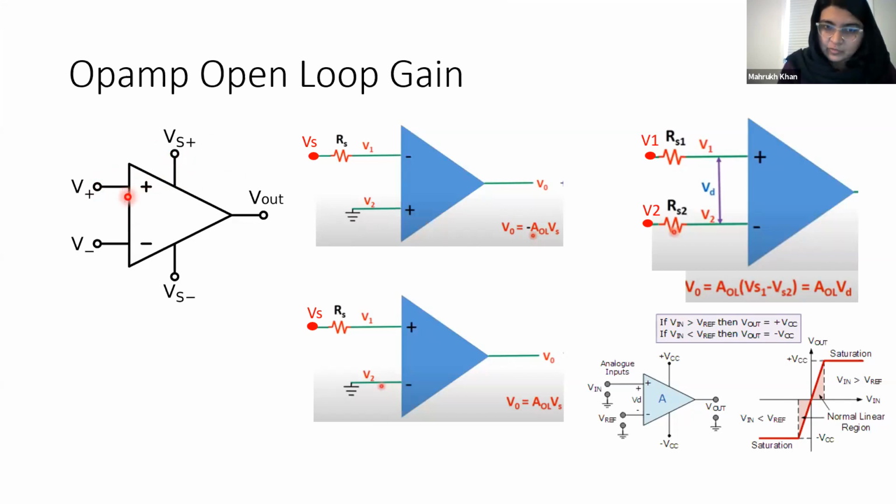If it is less than 12 volts, it will give you the logical result. Like if the output is supposed to be 4 volts, it's fine. But as soon as it becomes greater than VCC or minus VCC, it enters the saturation state, okay?